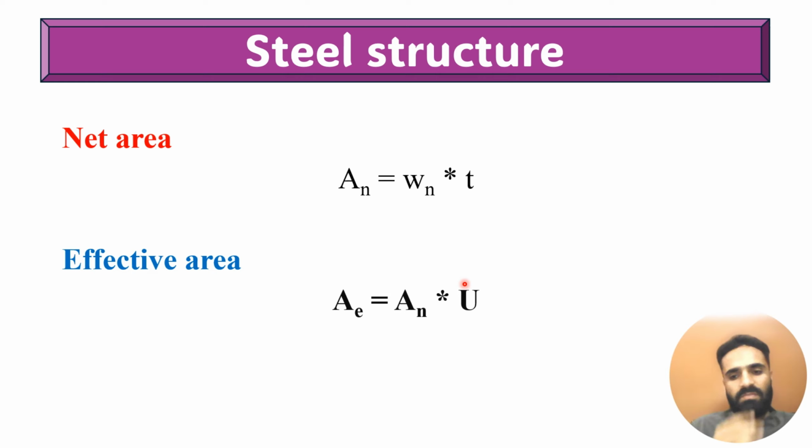There are 5 categories for finding the value of the shear lag reduction factor. Number 1 is the equation method. Number 2 is for plates. Number 3 is for hollow structural sections. Numbers 4 and 5 are the alternative values for single and double angles and for other shapes. So the net area of the staggered pattern and the parallel pattern are different. Remember this. This was today's topic.